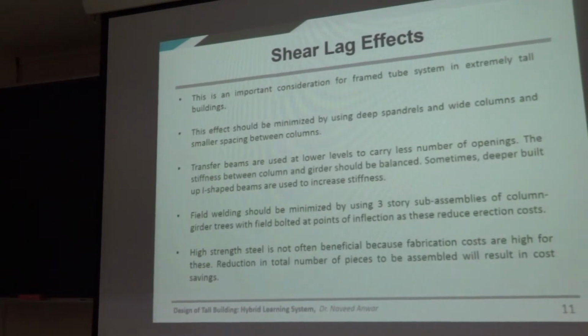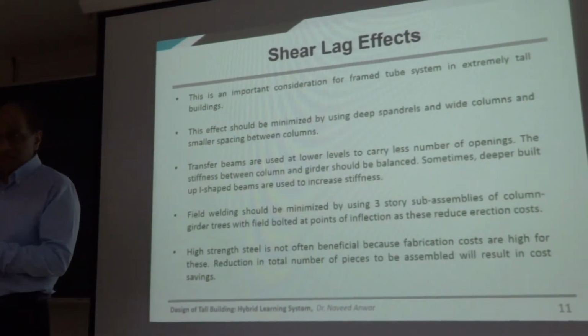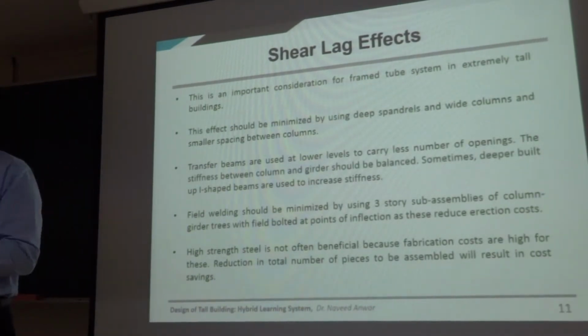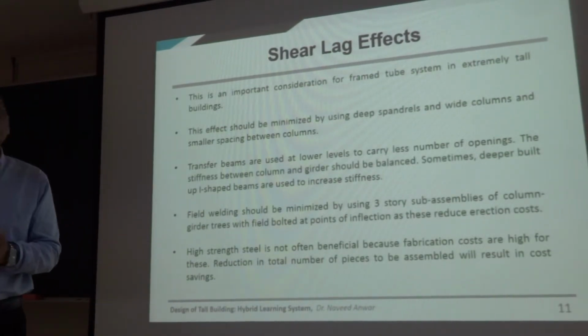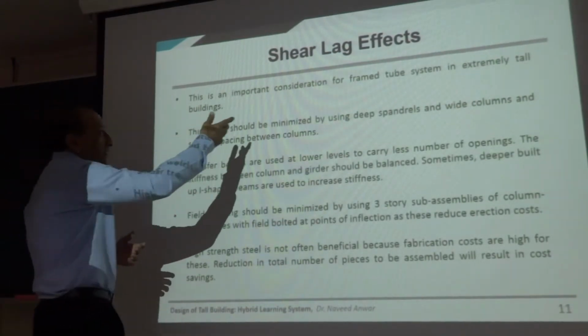Because of that shear lag effect, building deformations become larger than they should be. Because of that, the vibration or the initial period becomes larger than it should be, and the force distribution in the floor system becomes larger than it should be. So shear lag effect is something that we need to understand.